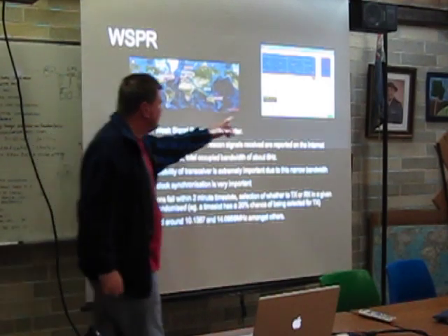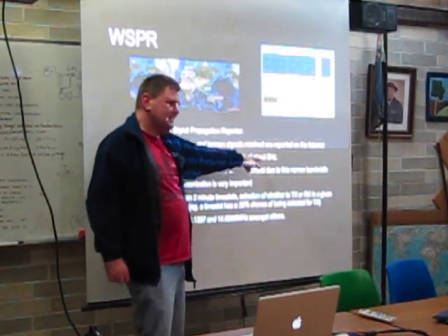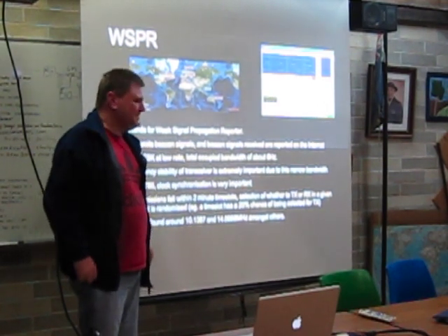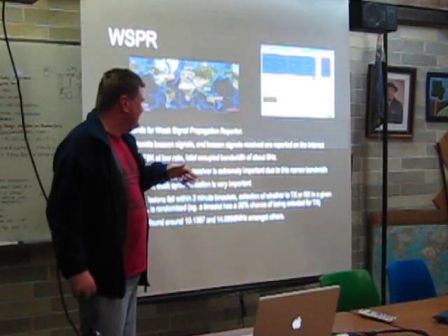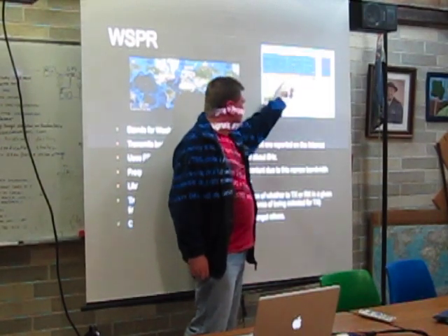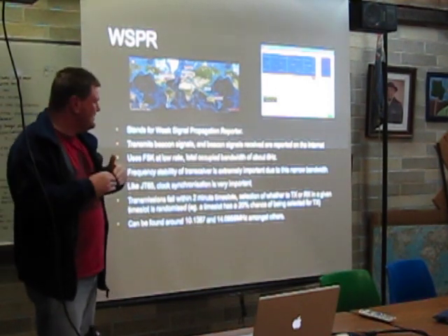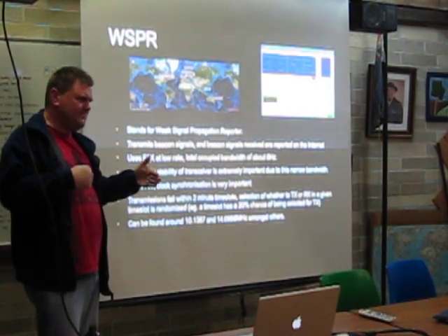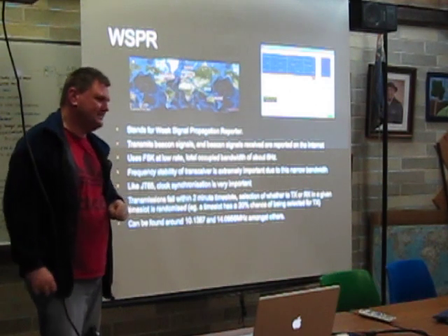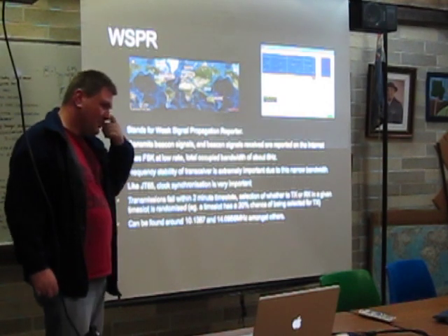The important thing is the stability of the transmitter. Because the width of the signal is only 6 Hz, if your transmitter is drifting 10 Hz even over the course of that 2 minute transmission, you're going to see it on here. The signals aren't going to be straight and horizontal, they're going to be going up at an angle, and you won't be able to decode. So within that 2 minute period, I think you've got a tolerance of about 4 Hz or something you've got to stay in for the signals to be reliably decoded. So it does put some stricter requirements on your transmitter.